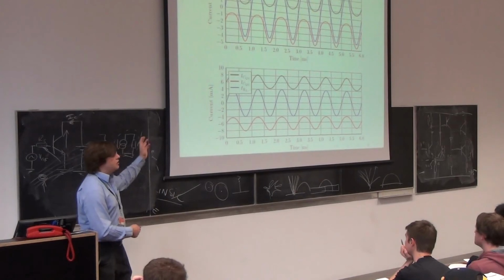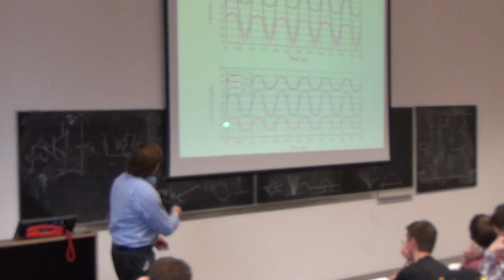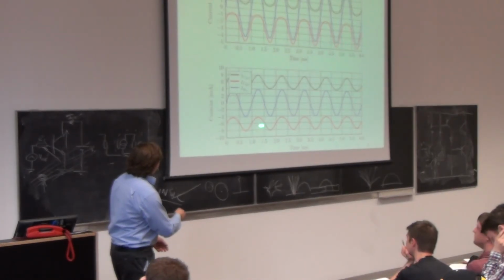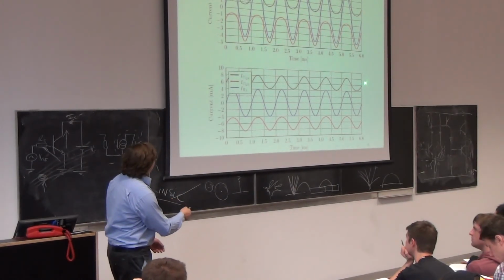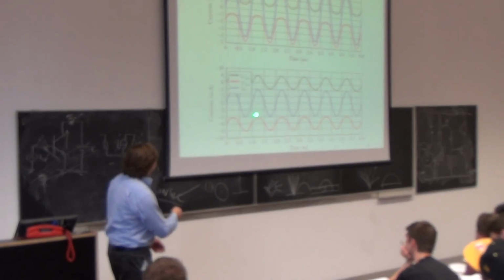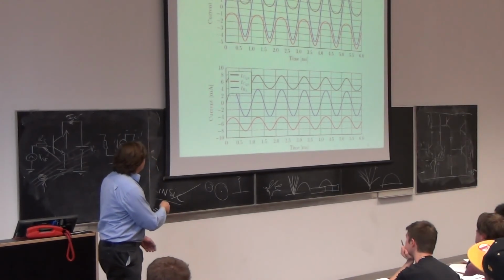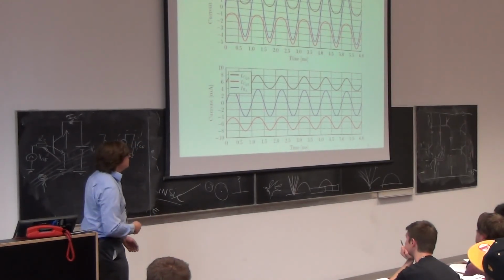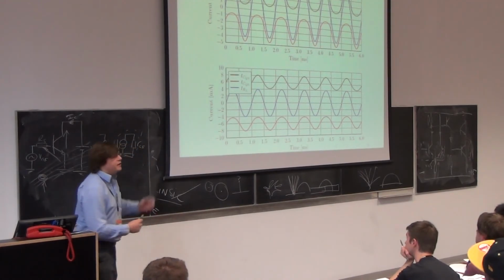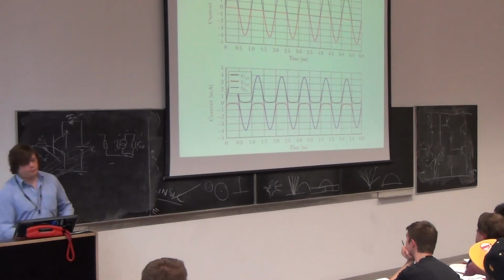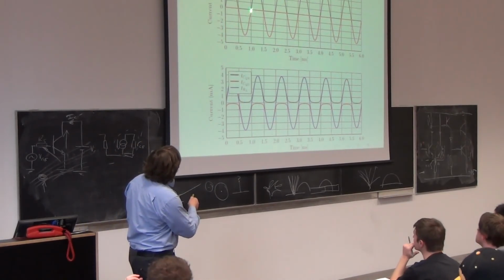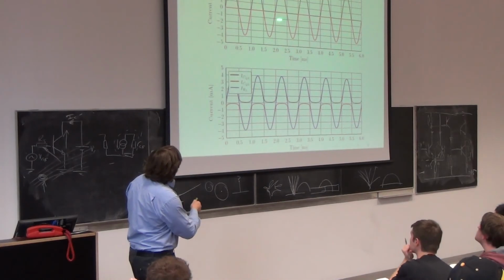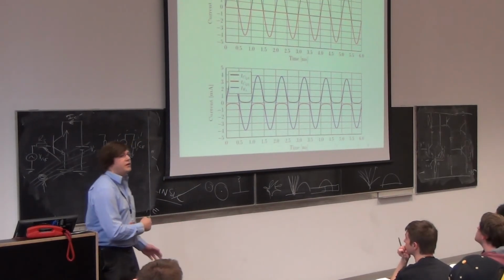If I turned off the sine waves and looked at this diagram, I'd have a line there, which is the current in Q5, and a line here, which is the current in Q4. And these lines are both above the maximum current I ever have in the load, just about. The load current would be zero under those circumstances. If I went back to the class B bit at the top here and asked what's the current if there's no signal, well, this is all to do with signal. So there are 3 lines on 0 and nothing more.